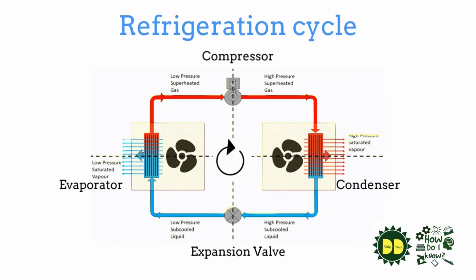After the expansion valve, the refrigerant enters into the evaporator. The evaporator is the heat absorber. In a typical air conditioner, the evaporator is placed in the conditioned space. As the refrigerant enters the evaporator, its temperature is lower than the conditioned space's temperature, hence heat flows from the air in the conditioned space to the refrigerant. Hence, the refrigerant gets the heat from the conditioned space and evaporates, and the conditioned space becomes cool. As the refrigerant leaves the evaporator, it is low-pressure, low-temperature, saturated vapor. After leaving the evaporator, the refrigerant enters into the compressor, and the cycle repeats.